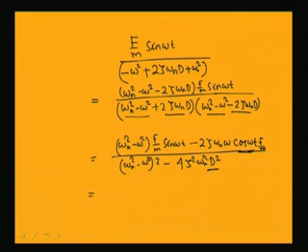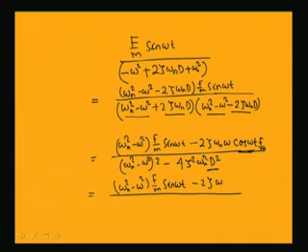So, if it is replaced by minus omega square, then this can be written as omega n square minus omega square f by m sin omega t minus 2 zeta omega n omega f by m into 2 zeta omega n omega cos omega t by omega n square minus omega square whole square minus 4 zeta square omega n square, and this thing can be replaced by minus omega square.